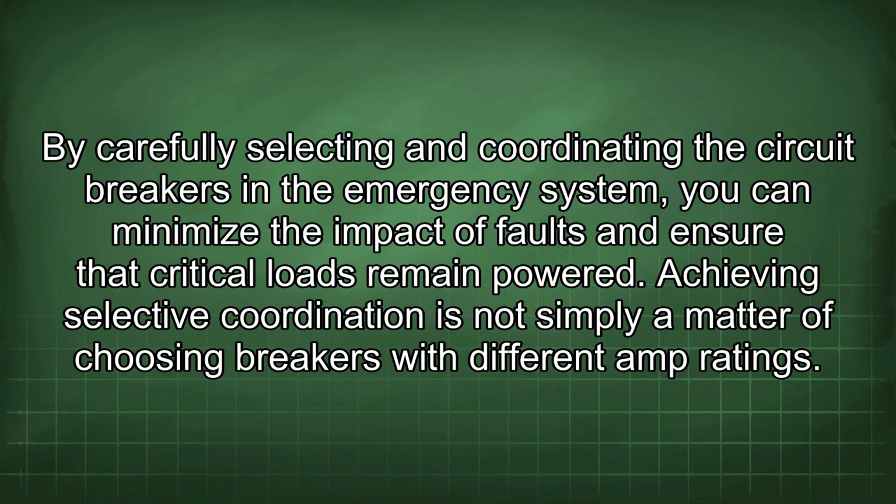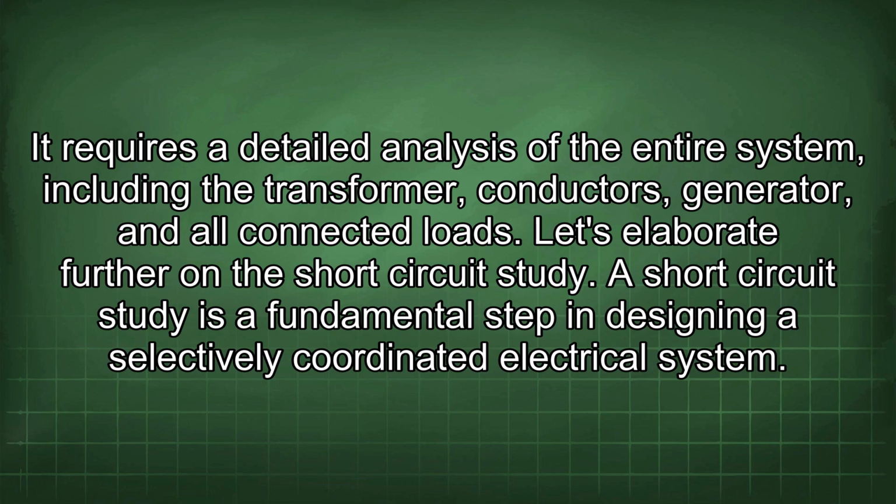Achieving selective coordination is not simply a matter of choosing breakers with different amp ratings. It requires a detailed analysis of the entire system, including the transformer, conductors, generator, and all connected loads. Let's elaborate further on the short circuit study.